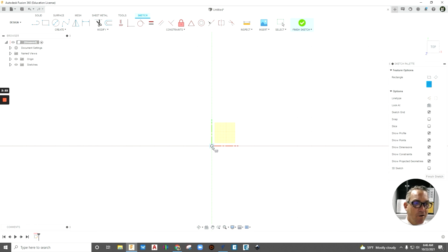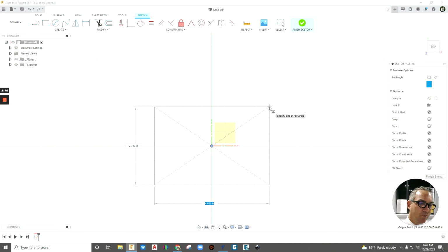You're going to hover over the center point here, so that you see that little blue rectangle showing up, and then you'll click the mouse once and drag up and to the right. Now don't click again. At this point, it's almost best to take your hand off the mouse. You'll notice down below there's a white box with blue highlighting. We don't need to click in there or anything. You can simply start typing the dimensions that we need.